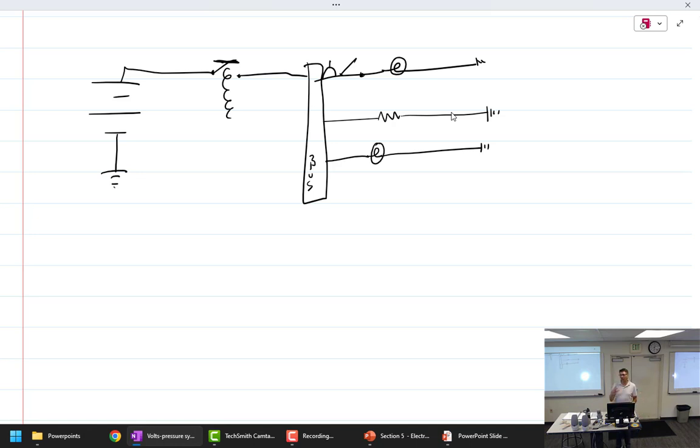But it's very hard to conceptualize that, especially when you're doing troubleshooting. If I had a break in a wire right here, I would not want to go, okay, it comes out of here, comes around. In a drawing you have to look all over for the ground. Oh, there's the ground over there, because the drawings have all kinds of wires, and then you kind of follow it through. It's just so much easier to go, no, it comes off here, goes to the master solenoid, master switch. Oh, the break is right there. So I'm telling you that to say it's a lot easier to conceptualize it going by conventional theory than the other way around.